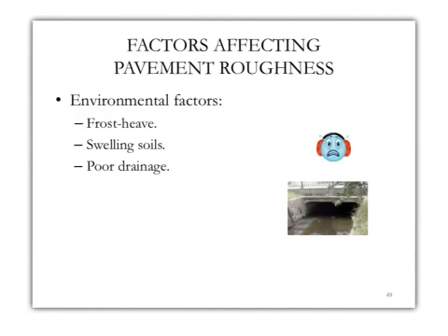Environmental factors. For example, if I have a frost heave or swelling soils or poor drainage, all those will definitely affect the roughness measurements as well, and I need to be aware of it before I go to the field and take representative roughness measurements.